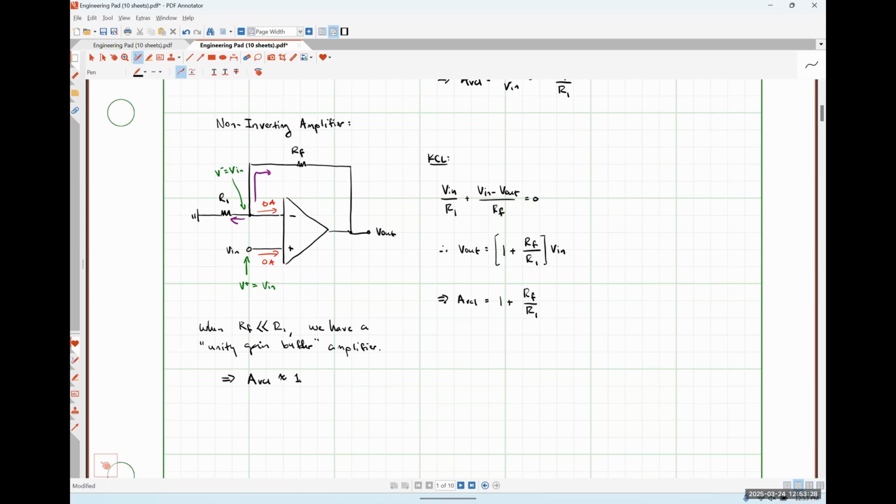The input of a particular sensor might be run through a unity gain buffer before it's run through an actual amplification stage, in a lot of biomedical applications and chemical process applications and things like that. So the unity gain buffer is a way for us to preserve our input signal while drawing power in from elsewhere to do other things, okay?